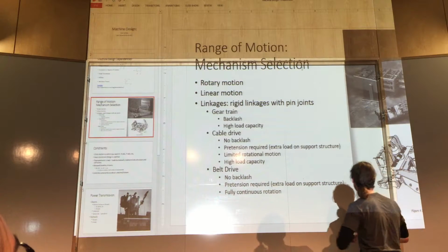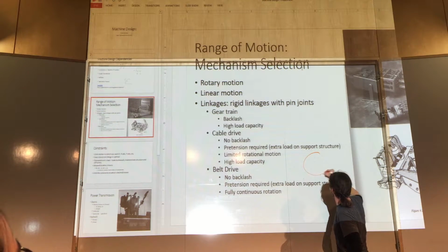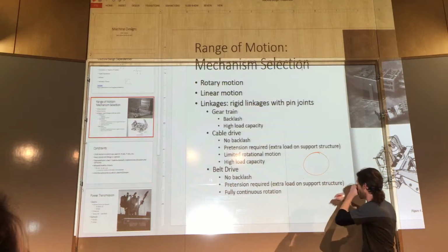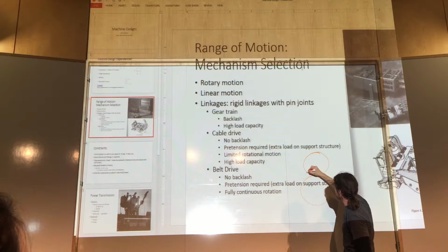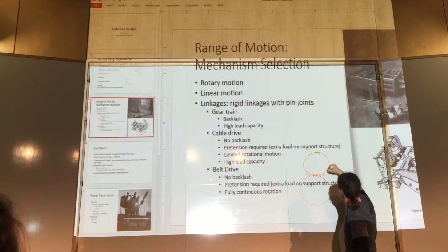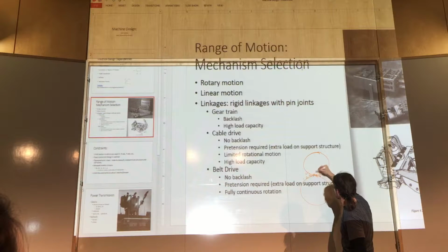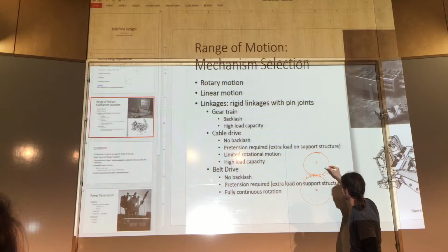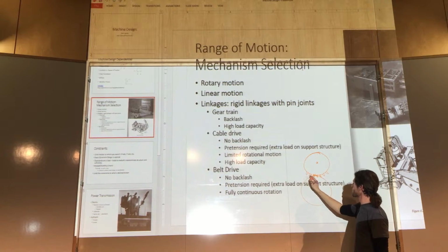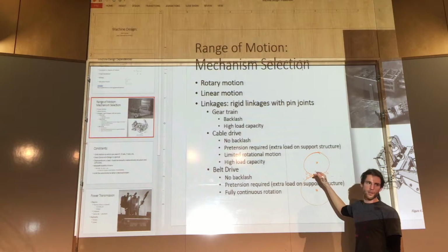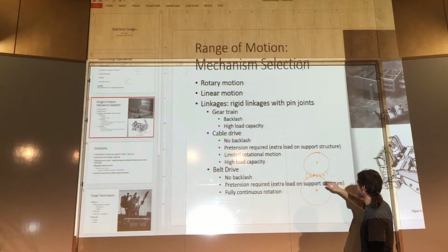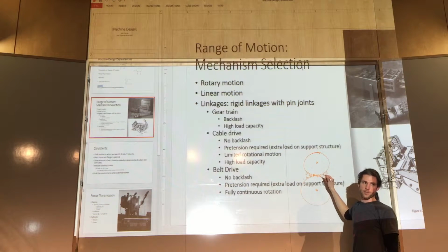Alright, let's see if we can do this. You see that? If you have gears, you've got these teeth all along here, and you've got them all along here. And you've got a center of rotation, and they're acting along some line. You can assume it's just a tangential line here, but usually there's some contact angle on the gear teeth. Usually it's 20 degrees or 14.5 degrees.